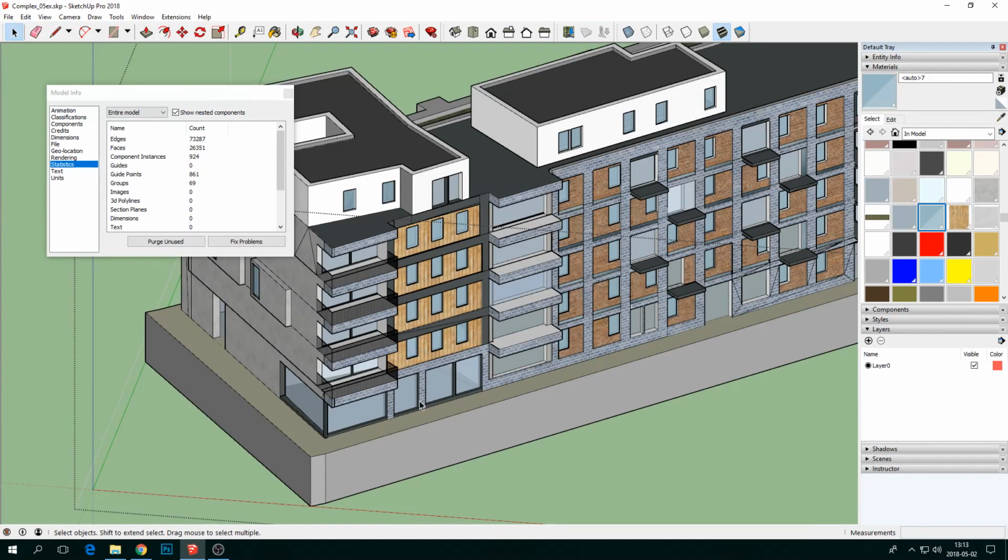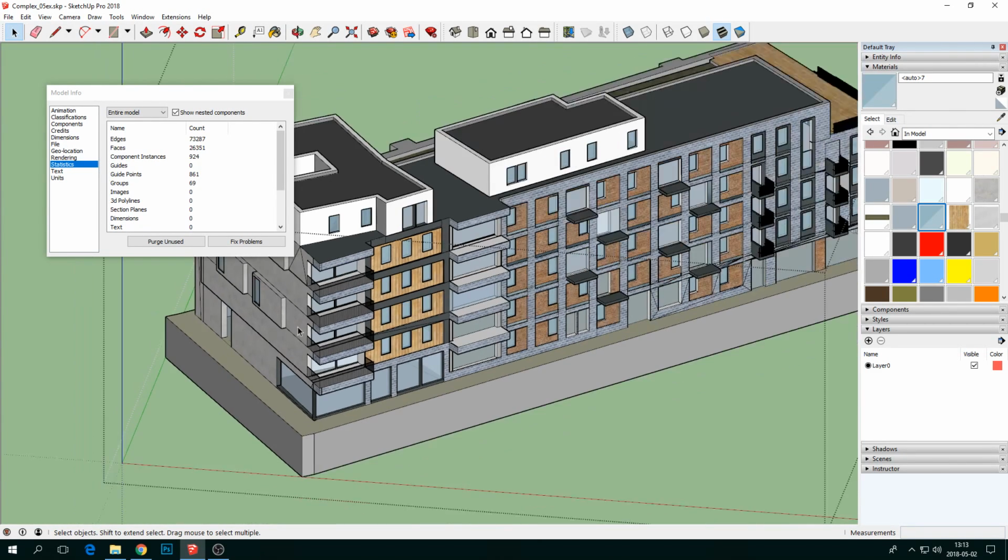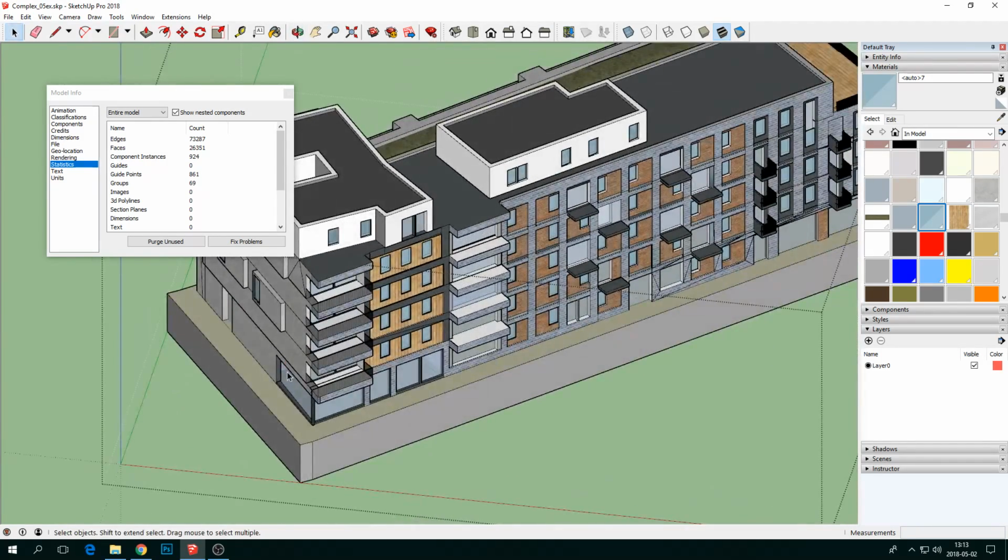And another thing to consider when it comes to transparent surfaces is that they actually have quite an impact on rendering performance. So if you have a lot of transparent surfaces, you might get slower rendering of that model. So make sure to only use it when there's a purpose. Exactly. And the next step here is textures, actually.